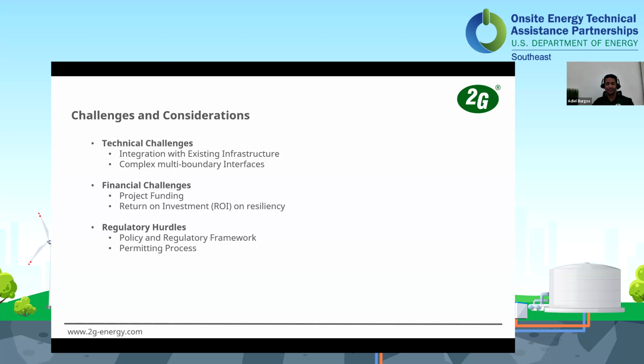And the return on investment and resiliency: return on investment for the systems comes in obviously with the cost that there is, but resiliency costs additionally. Meaning having, what we call in the industry, N+1, so another engine in the configuration to ensure that if one engine goes down, you can keep running. Then there are design considerations for island mode, which means if the grid goes down, you can keep running. That has an additional cost. And sometimes having that resiliency captured as a value is hard to get across to the customers.